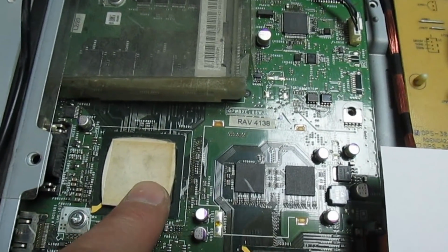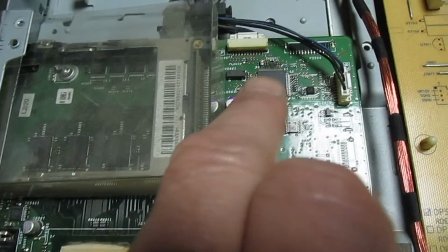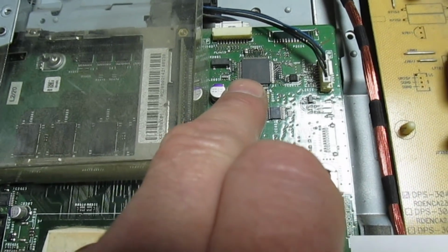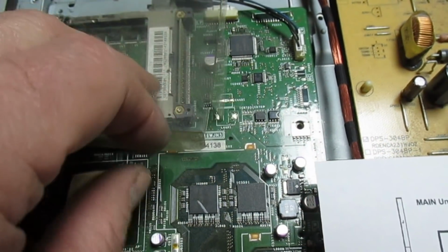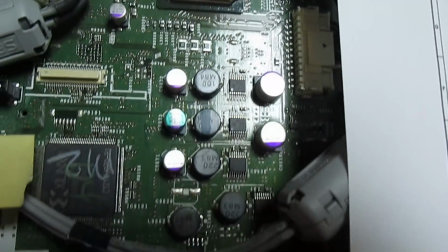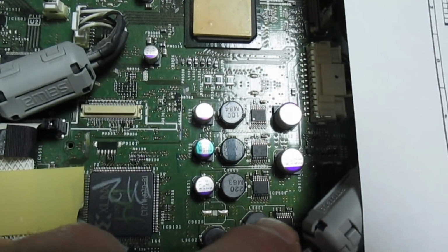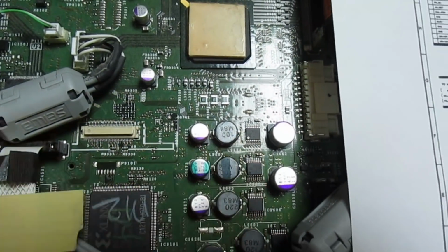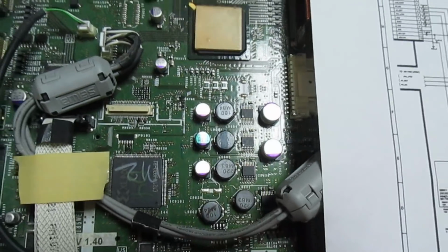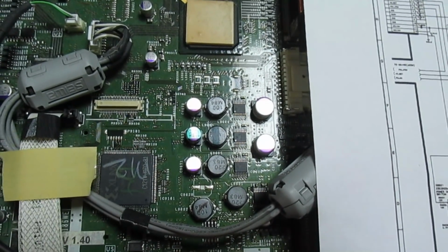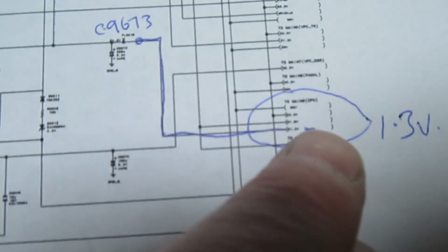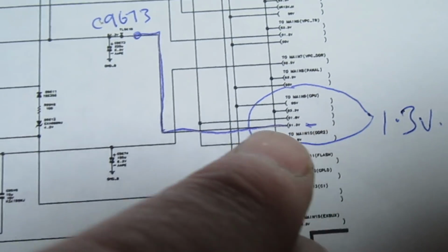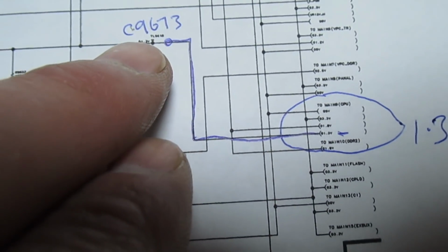Right, so that's the main CPU, the BGA. That's the submicro. The service manual says there's no communication between the main micro and the submicro. If we look down here, the DC converters, these are the ones that generate the low voltage rail, and straight away I found a discrepancy. So if we move over to the service manual, I'll blow this up on the computer, I'll show you bigger. We should have 1.3 volt there across